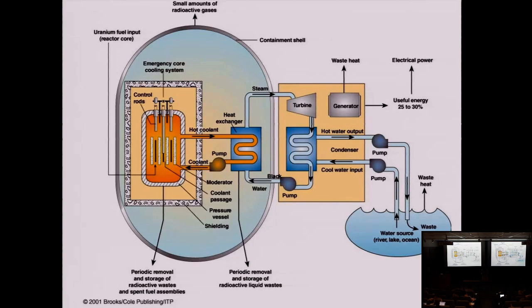The other thing you do is to increase the propensity of the water to have dissolved solutes in it. What that means is that the warmer water is, the more it dissolves things. We've already talked about water's tremendous capacity to dissolve things. You expand on that when you heat water. So there could be metals, there could be toxic things, organics, sitting harmlessly in the sediment beneath or downstream of the cooling tower, and adding heat in will mobilize them, make them biologically able to be taken up, and put them into the food chain.